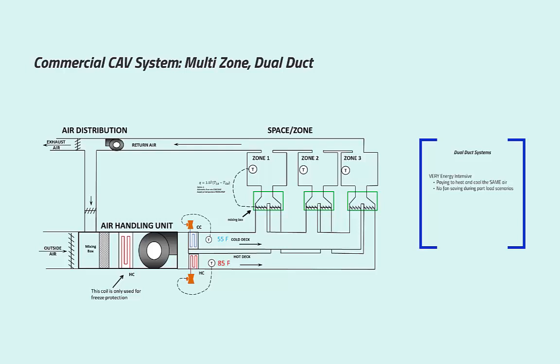These systems are becoming less common, but they still exist, even in the Air Force. I will say this, there are ways to retrofit these constant volume dual duct systems into variable air volume dual duct systems, which would inherently save some fan energy. However, such a retrofit gets complicated very quickly, and describing how this would look is a little beyond the scope of this course.